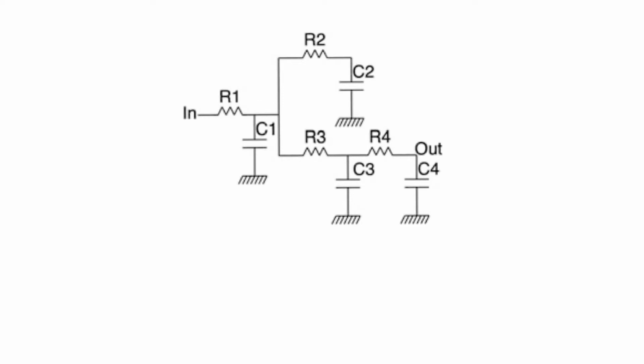It only works when you have feed-forward paths which have resistances and you have capacitances to ground. So you cannot have a feed-forward path that has a capacitance in it, because in that case you'd have coupling. And you cannot have loops. You only have to have a tree network with outgoing branches and feed forward. So let's, for example, calculate the Elmore time constant at this output node, output, for this input node, in.